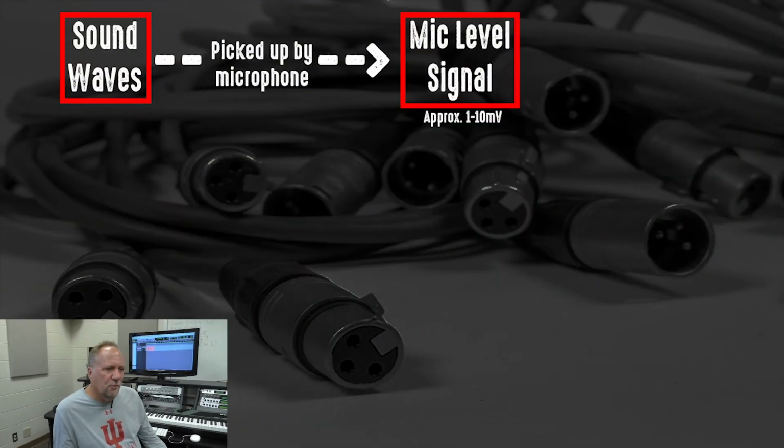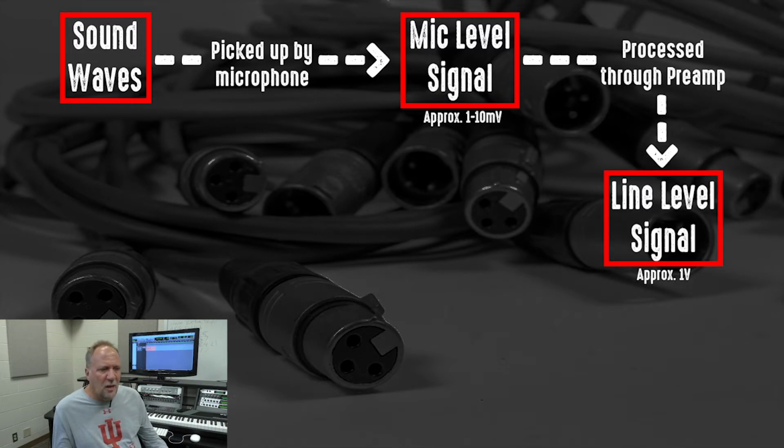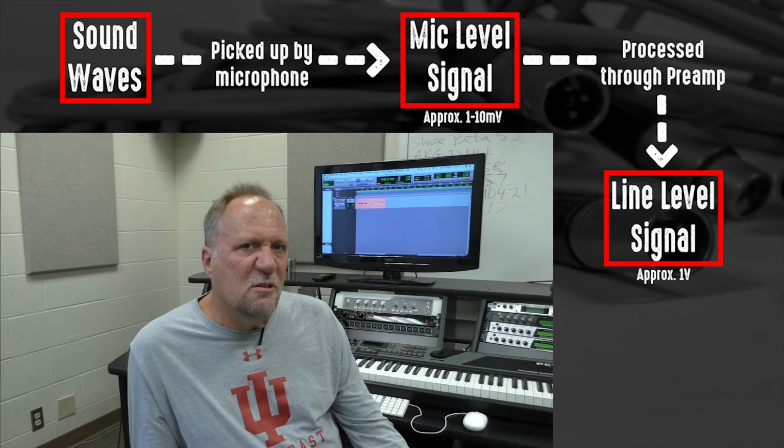It's really, really weak, and lights, radio towers, cell phones, all that stuff can infiltrate this signal and cause problems with it. Your first device in your gain stage is called a microphone preamp. Its job is to take this millivolt signal and bring it up to what's called line level. Line level is approximately 0.7 of a volt. So if you took the line output from a mic preamp and stuck it on your tongue, you'd still look weird and you still wouldn't feel it.